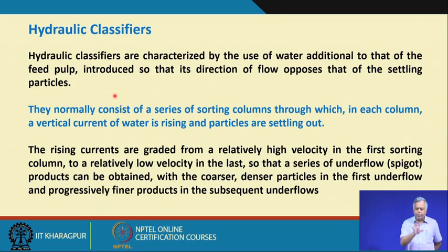You are feeding the pulp, but as we mentioned, in a hydraulic classifier you are also adding water in the opposite direction of the particle movement. That means the particle is trying to settle, and you are providing an upward velocity of water. That is the demonstration we gave in the movement of solids in fluids lecture, in the very first lecture I gave on this topic.